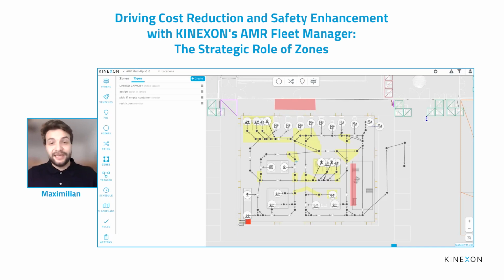And as I said, the last thing is the zones give the fleet manager the flexibility to very easily set up behaviors in certain areas, because they can just say, okay, in all of that area, I want to have a speed limit. Or in all of that area, all of those points should be disabled, or stuff like that. Because you actually shouldn't care that much about the points and the paths, but you want behaviors in areas. And zones are the modeling layer that is totally crucial to it, because otherwise it's going to be so much clicking to set everything up. And in the long run, you need it anyway for the robots that need more autonomy. And exactly for that, we offer zones.